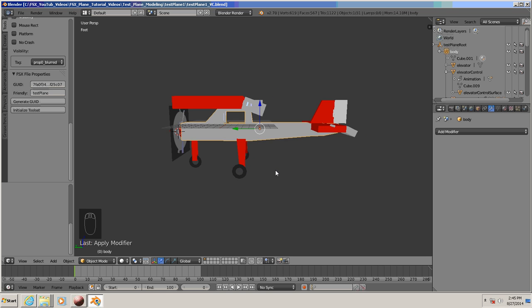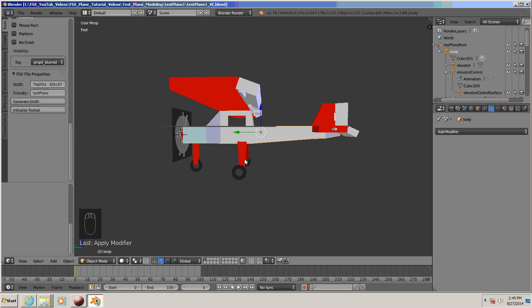First we're going to remove some things because we don't need to have the landing gear, the wheels, or the back rudder or elevator. We want to make our virtual cockpit as small as possible, because in most virtual cockpits you start using a lot of vertices or a lot of polys in modeling your virtual cockpit. You don't want that being so high, so you need to get rid of everything you can that's not needed. You'll never see your rudder, you'll never see your elevator, or usually you'll never see your landing gear because of where your viewpoint is.